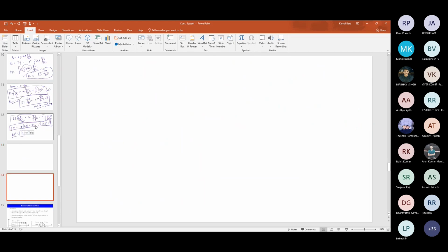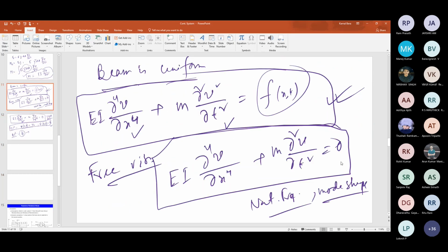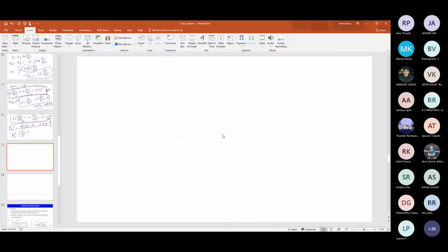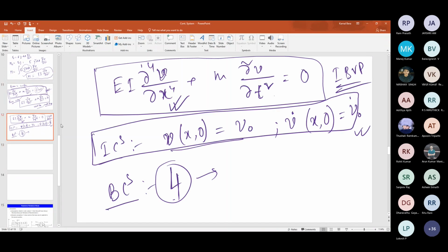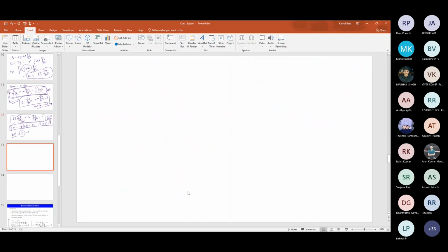If you have used Hamilton's principle, you could have seen that you obtain the same differential equation, along with all the combinations of the boundary conditions also. That is the beauty of the method. But here you are not getting that, so we'll talk about it explicitly. The 2 initial conditions are done. Now the 4 boundary conditions. So what are those 4? We'll talk support by support. At each support there are basically 2 boundary conditions, because the beam has 2 supports.